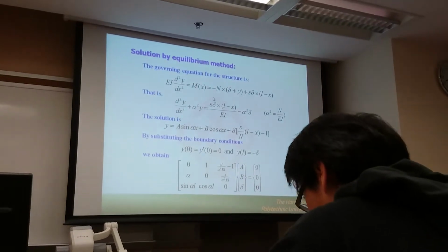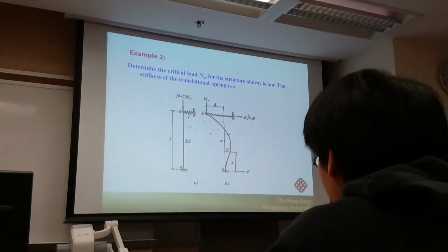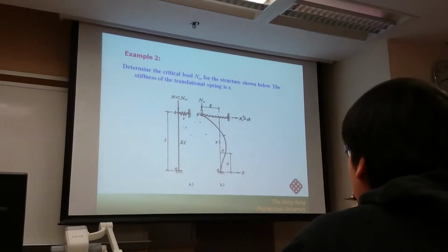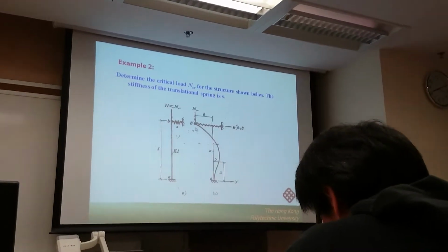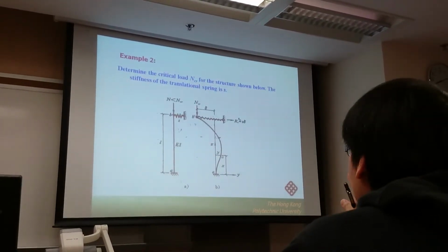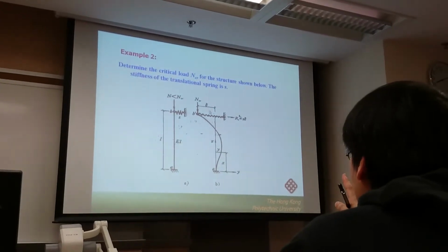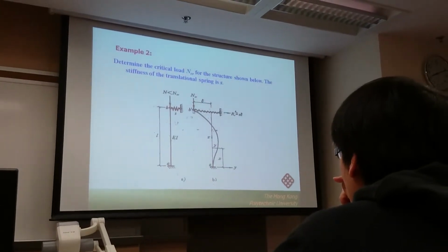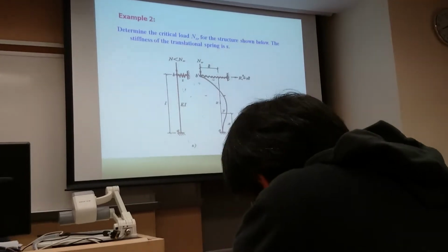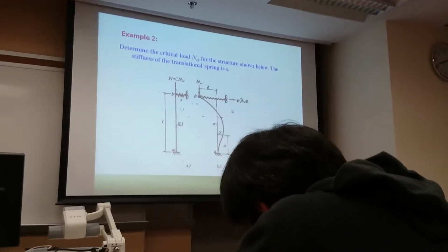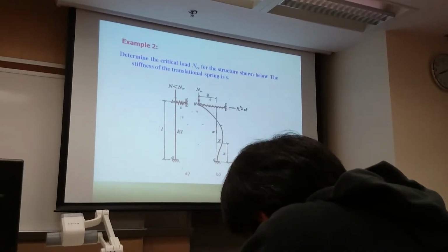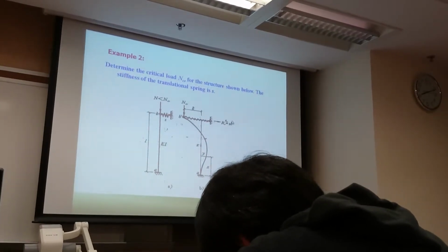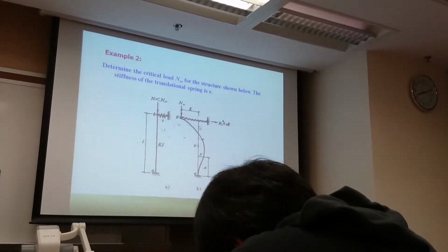The equation I provide you is that we cut off any cross section. And then the moment due to this force is equal to the force times the distance between B and this point. The distance between B and this point is equal to delta plus y. But please understand, delta must be positive. It is not an ordinate. If this is negative, delta plus y is not equal to the total distance. So the total distance is equal to positive delta plus y. For the reaction force, it is equal to the reaction force times the distance L minus x.